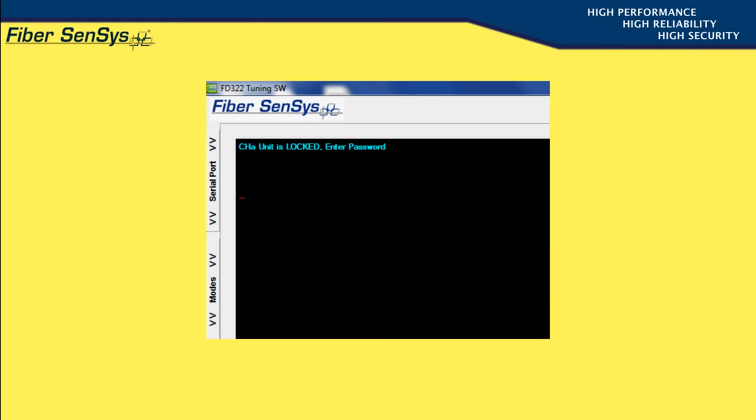To measure the loss or calibrate the unit, access the Calibrate menu and type ML and enter. If you respond with Y when asked, "Are you sure?" the display shows the last measured loss value, and at that point you can perform the measurement and calibration processes. Again, this procedure is explained in a video segment that is shown in the calibration and tuning section of this training program.